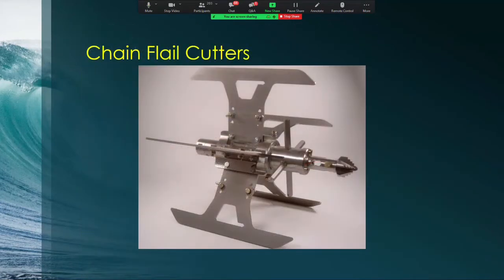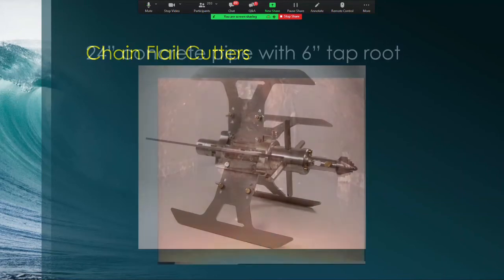Okay. When it comes to chain flails, root cutters, and things like that, we can provide you with chain flails and root cutters to go from 2-inch pipe all the way through to 48 and beyond. This 48-inch configuration, this nozzle here in front of you, is configurable from 6-inch through 48-inch and can go up to, I've had it as big as 10 feet in some instances. You can turn that into cutting minerals. You can cut roots, protruding surfaces. Anything you have to have happen can happen from here.